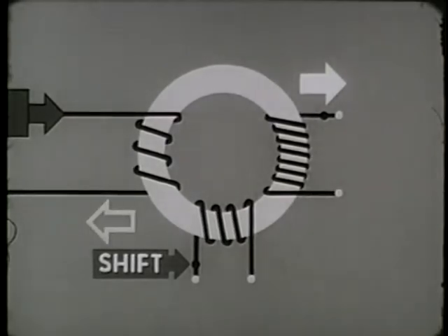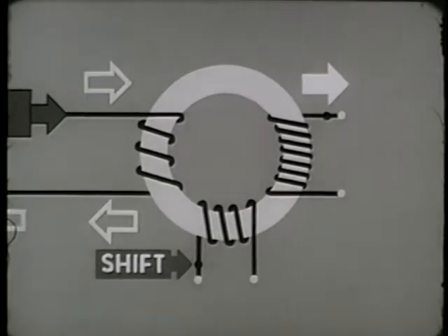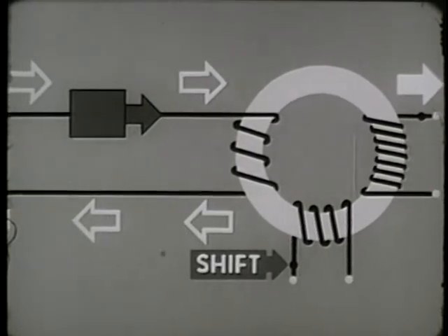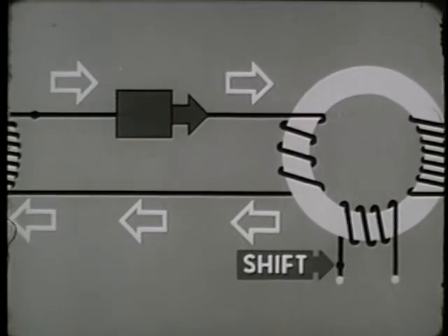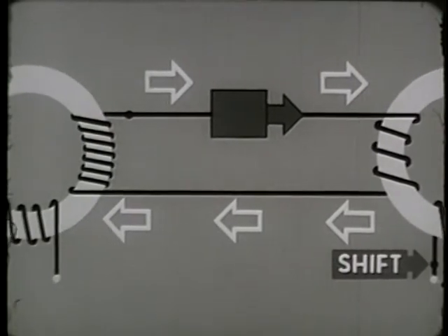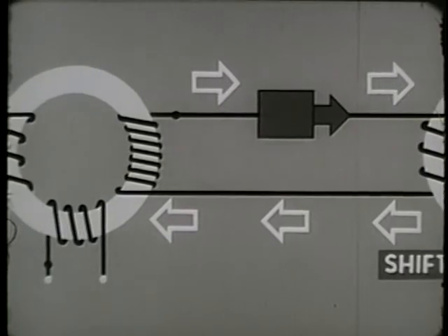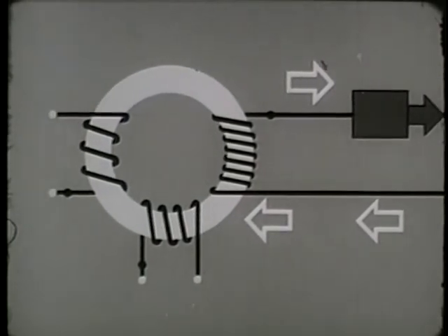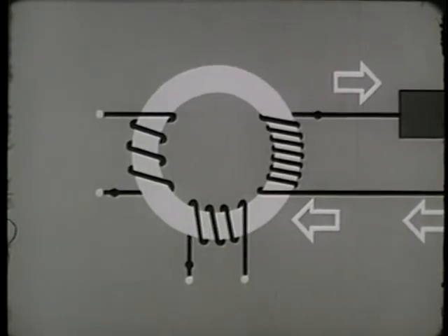Current will flow out of the dot side of the input back toward the first core. The one-way device won't stop it because it's going around the circuit in the direction it allows. This backward flow of information would, if unchecked, switch the first core, interfering with its operation. It is checked, however, by the design of the output winding.